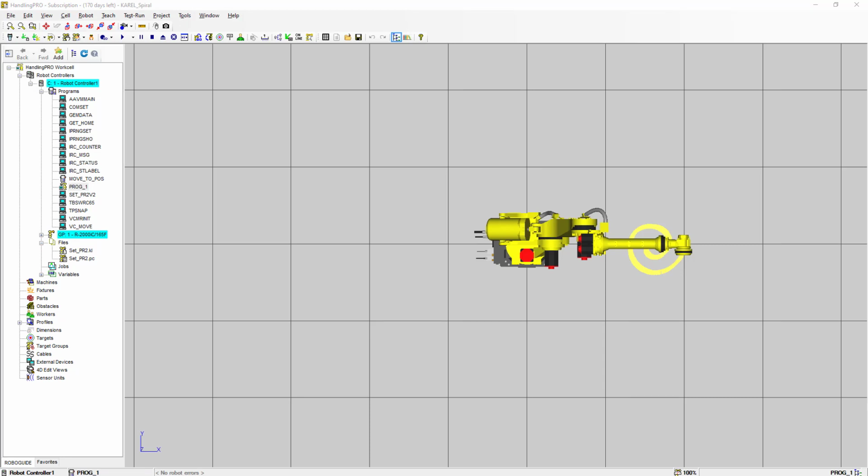Before I conclude with the presentation of this video, I want to give you a few assignments. First assignment, get the KAREL reference manual and read about all the KAREL instructions that we have used in this program, especially the position data types that we're using. You're going to find that there are different types of position data available. Second assignment, you can modify the program and add a linear motion on the z-axis.